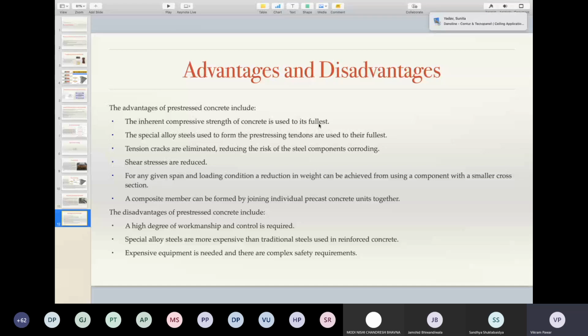Now we use very high strength concrete, M80 and above, particularly for skyscrapers, and they are pre-stressed. Pre-stressing is not just about beams and slabs. It is used for playing fields like basketball courts. It is used for high-rise buildings, tall skyscrapers, where the vertical cantilever, the column members, are pre-stressed, so that the column dimensions are lesser and you are able to use high-strength concrete.